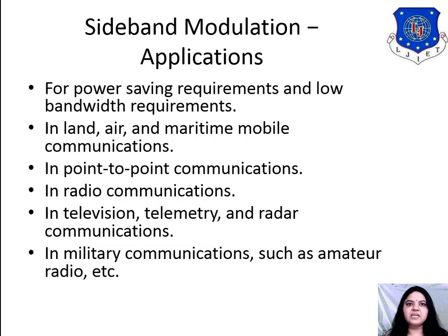The various applications of the SSB modulation are there. The very first thing that we discussed is the power saving. So for power saving requirement and low bandwidth requirement applications, we must go for the single sideband modulation.